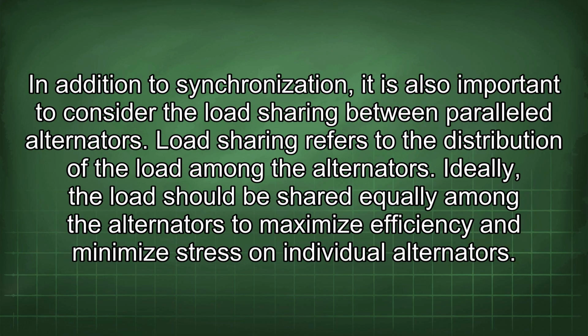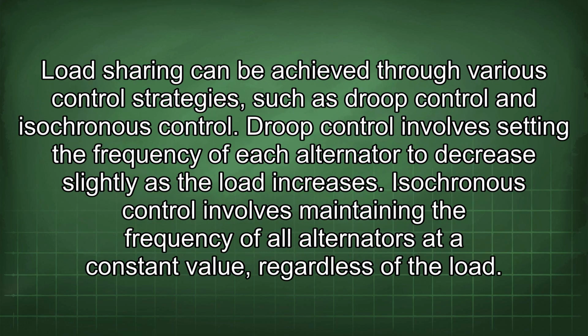In addition to synchronization, it is also important to consider the load sharing between parallel alternators. Load sharing refers to the distribution of the load among the alternators. Ideally, the load should be shared equally among the alternators to maximize efficiency and minimize stress on the individual alternators. Load sharing can be achieved through various control strategies such as droop control and isochronous control.